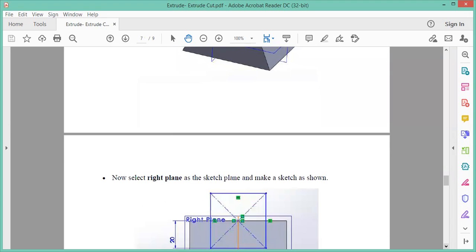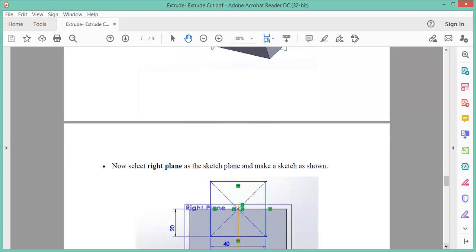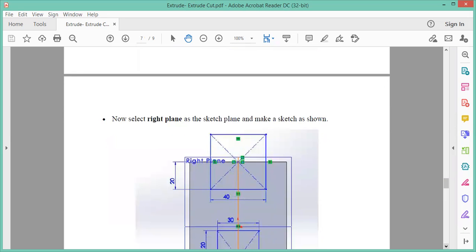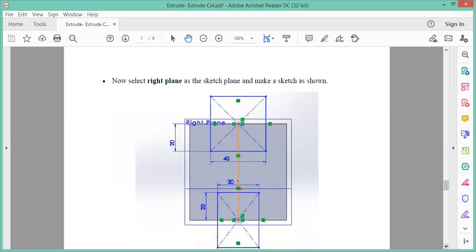Now next, you are supposed to remove some material to model the part that is your problem part. So for that, you will make use of the extrude cut command. As in the case of extrude, you need a sketch. For extrude cut also, you need a 2D sketch. Again, in a plane, you will have to draw a suitable sketch that is to be used in the extrude